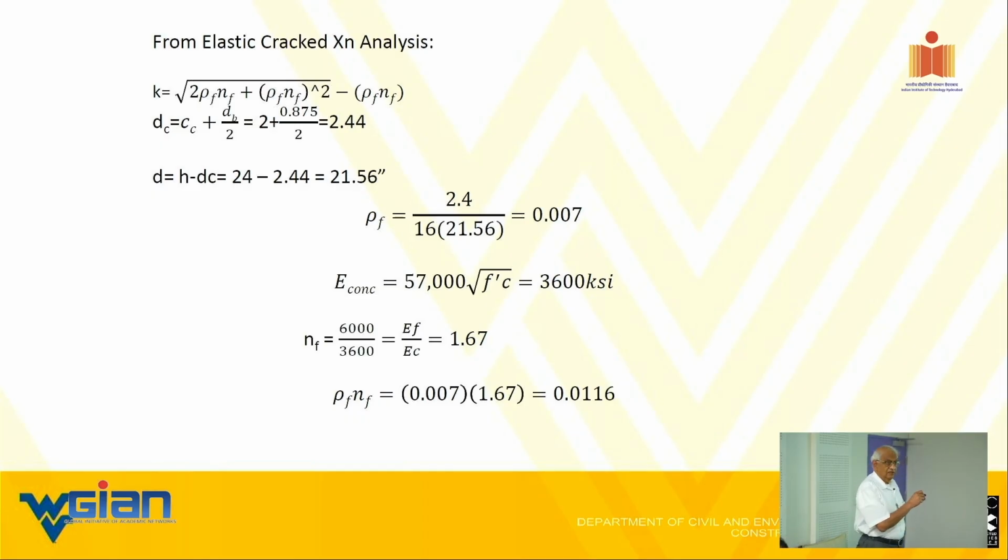So again, the d value, the effective depth for this beam is given to you there, and the modulus. We have 2 equations to establish the modulus of a concrete based on f prime c. This is an easier equation, 57 times square root of f prime c, slightly less accurate than the other equation.